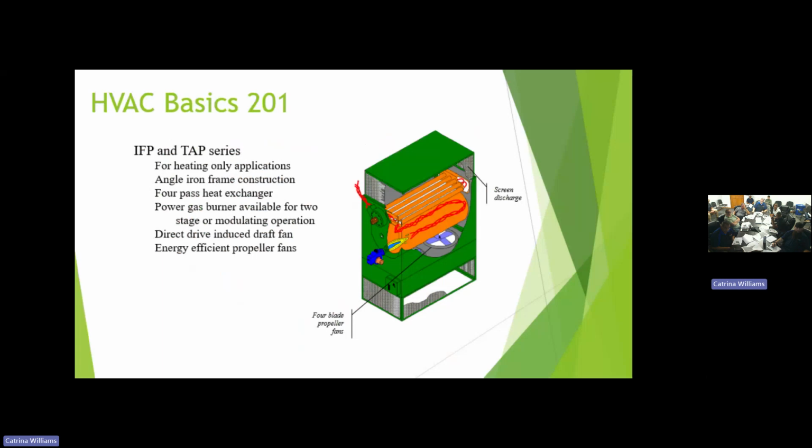Now let's go back to this morning's session. We talked about standard air. What's the weight of standard air? Can you remember that number? I gave you a weight per cubic foot. Standard air weighs 0.075 pounds per cubic foot. That's again based on standard air at sea level conditions. Yes. There you go.